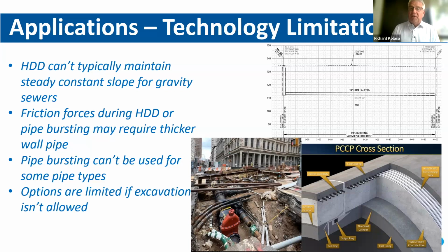But that also contributes to your installation aspects as well, because the surface area increases with that thicker wall profile, you get better tensile strengths to be able to pull that in longer distances as well. Okay, great. And you'll see here in the bottom picture, of course, that's everybody's nightmare in a very dense city that's just built and built and built over time. There's very little trenchless that you could do in these applications to be able to come through and install it.